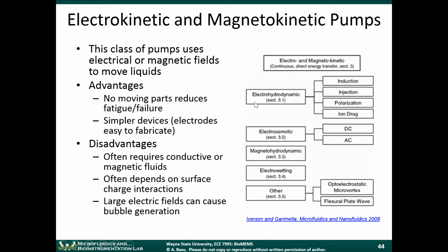So this chart shows a summary of some of the different types of electrokinetic pumping methods. Electrohydrodynamic mechanisms add some type of electrical energy to the fluid. Electro-osmotic pumps rely on the interaction of the fluid with the channel walls. So we'll talk about each one of these, and then we'll mention a little bit about magnetohydrodynamic pumps as well.